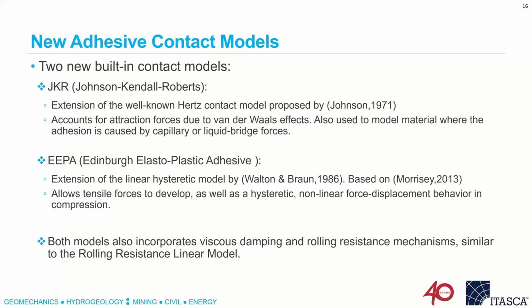We also have 2 new built-in adhesive contact models that have been added to PFC7. One is the Johnson-Kendall-Roberts contact model, which is an extension of the Hertz contact model that accounts for attractive forces due to van der Waals effects. But it is also used in the literature to model materials where adhesion is caused by capillary or liquid bridge forces.